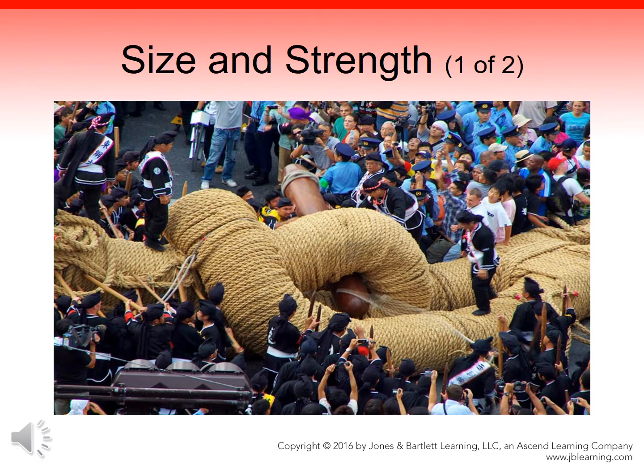Size and strength. The strength of rope, also known as tensile strength, depends on its cross-section of material, or the amount of yarn used per foot of length. The larger the diameter of the rope, the more difficult it is to manipulate. This is also termed as the hand. A rope that is difficult to manipulate is said to have a strong hand. The stronger a rope is, the less it stretches. A lack of stretch means poor energy absorption when force is suddenly applied to the system.